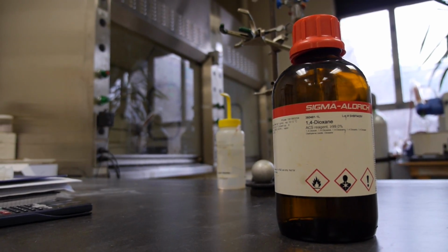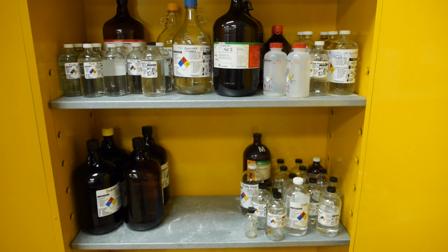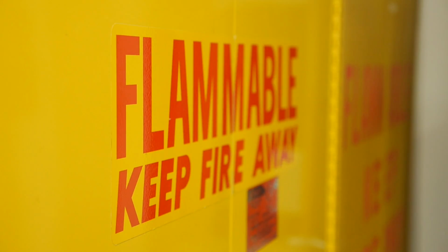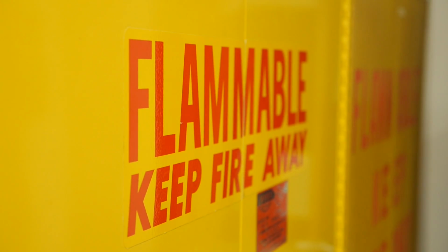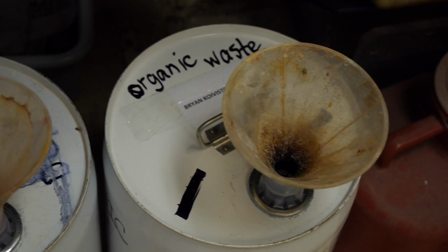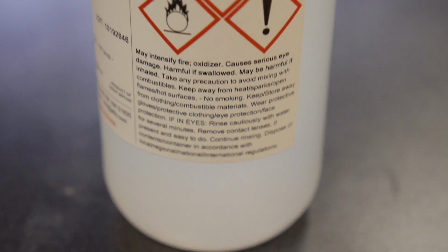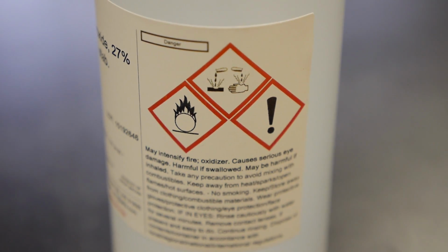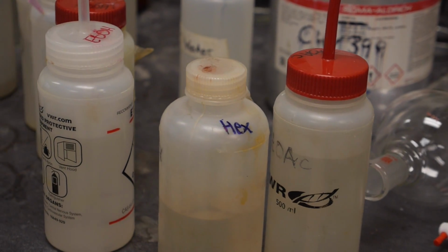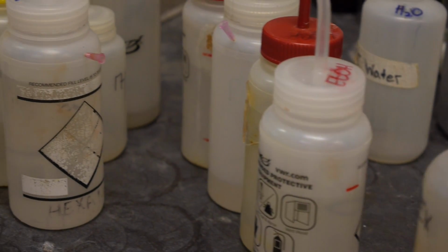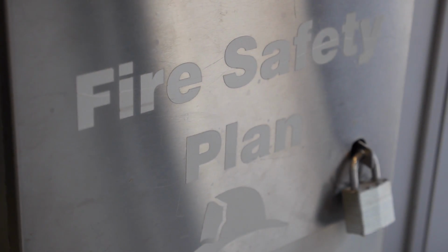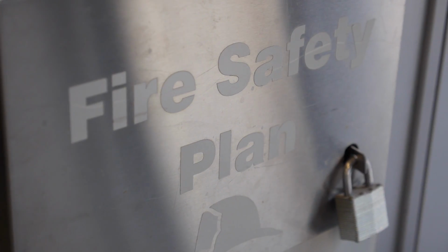Flammable and combustible liquids must be kept in proper storage at all times, such as flammable storage cabinets, making sure that all storage containers containing flammables are labeled with a conspicuous flammable symbol or wording. Flammable and combustible liquids should never be stored alongside corrosives, oxidizers, reactive chemicals, or compressed gases. It's very important to note that the storage volumes of combustible and flammable liquids must not exceed the allowable limits as prescribed in the Ontario Fire Code regulation.